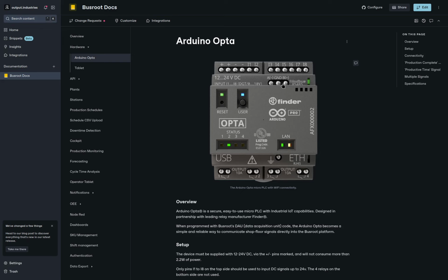If that's not an option, either because there is no PLC or the data isn't available in that PLC, or we just simply don't want to interface with the PLC, it can also be used directly with sensors that are on the equipment already. So a typical example of what we might do with a customer is an andon light. I've mentioned that before. So the andon light can be linked to this device so that we can also read what that's doing. From the andon light, we get asset utilization and we can get production cycles.